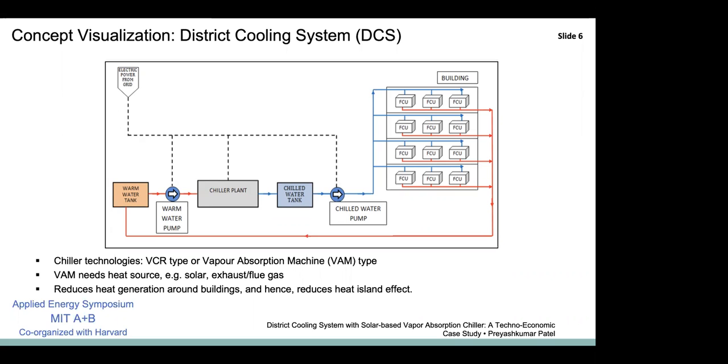To produce the chilled water, the chiller plant requires low-grade heat energy. That need can be satisfied with solar energy using various kinds of collectors, or biogas or sewage gas in an eco-friendly manner. For a continuous flow of chilled water supply, a chilled water or hot thermic fluid storage tank can be provided.